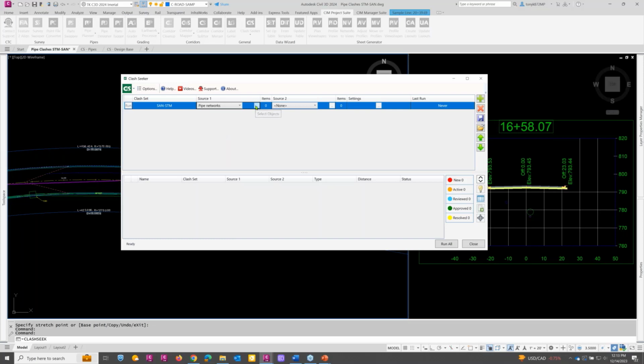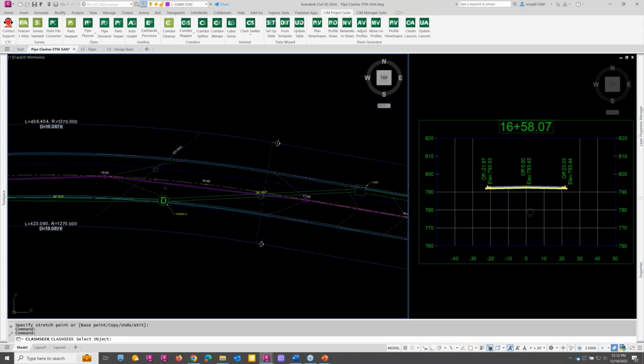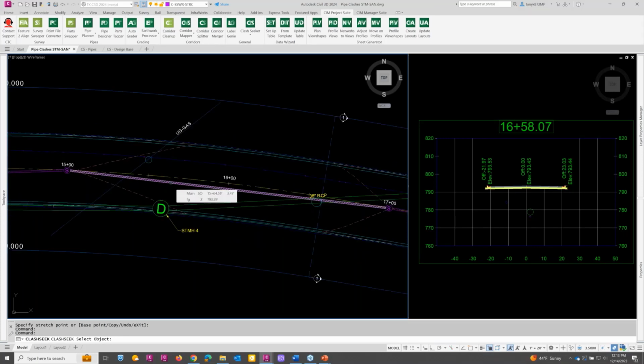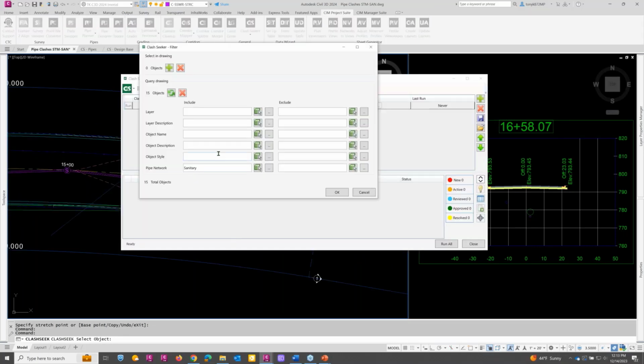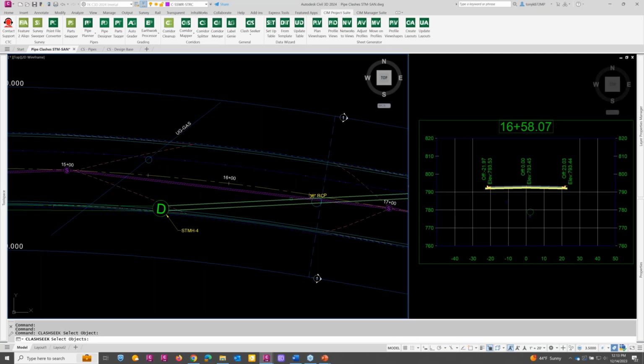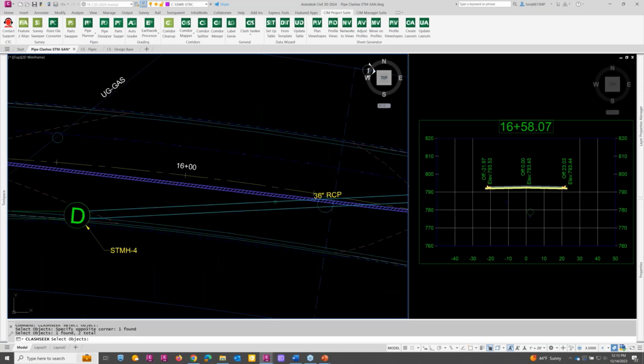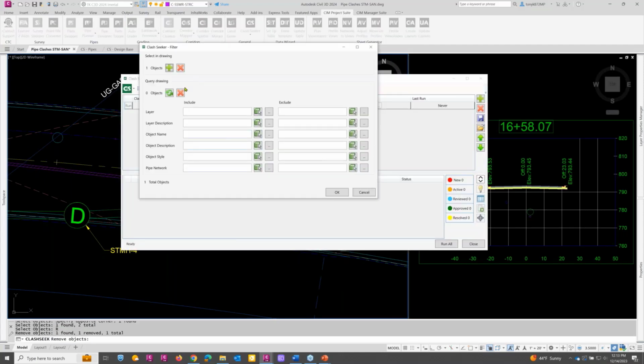And we're going to compare the two pipe networks. So here's where we pick where our pipe network is. And we can do it one of two ways, actually three ways. So we can do the whole network. We can do parts of the network. Like clear that out. We can pick just these right here that we think might have an issue. Let me remove that one, so that's a separate one. So we can do it that way too. Let's do the whole network today.